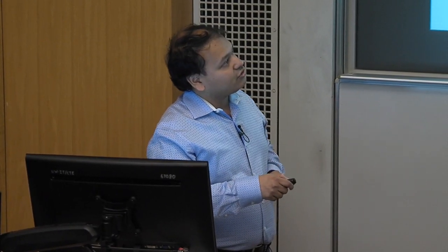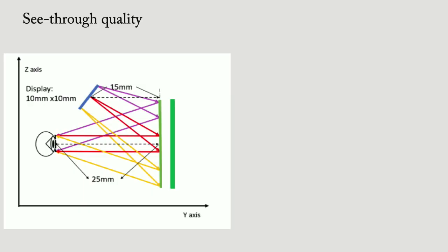The virtual world looks fine, but your real world has to come through that metasurface, and it's going to look very distorted. So we realized that we can actually solve it by using another metasurface, and this metasurface is 100% transmissive. When the light comes in, this metasurface pre-distorts the light, which gets distorted again by this other metasurface, and together they don't have any wavefront error.